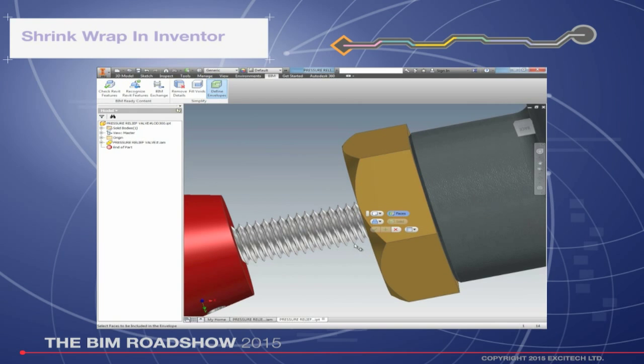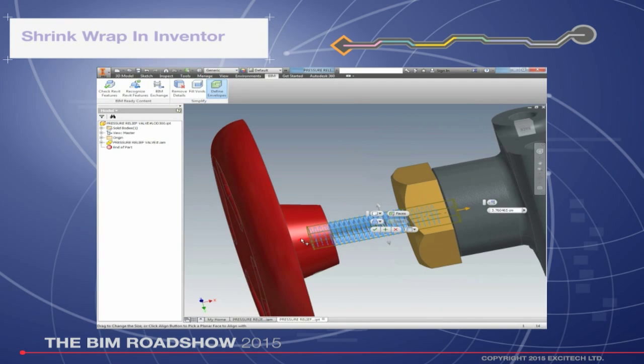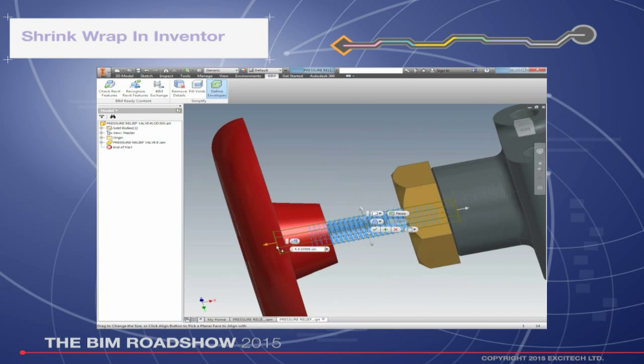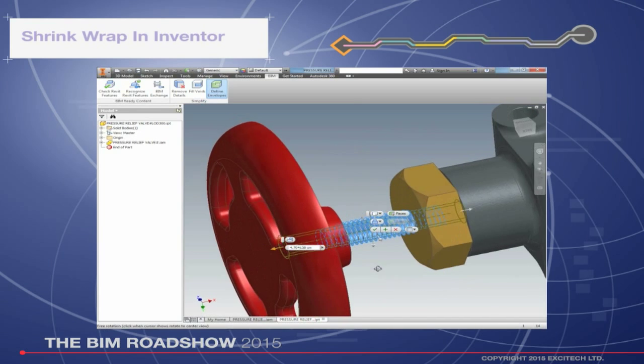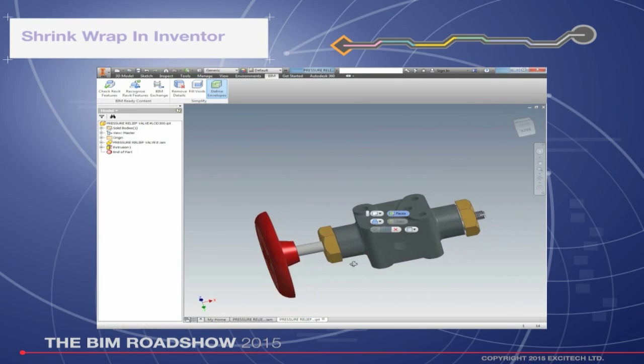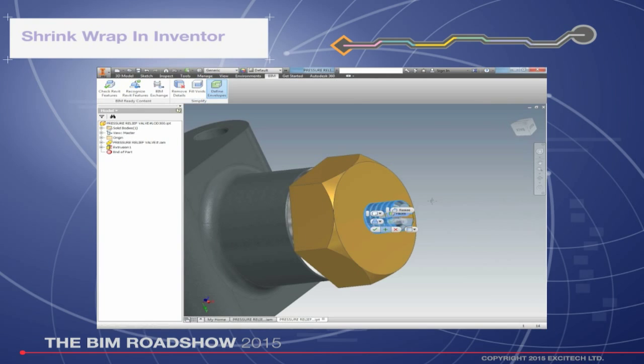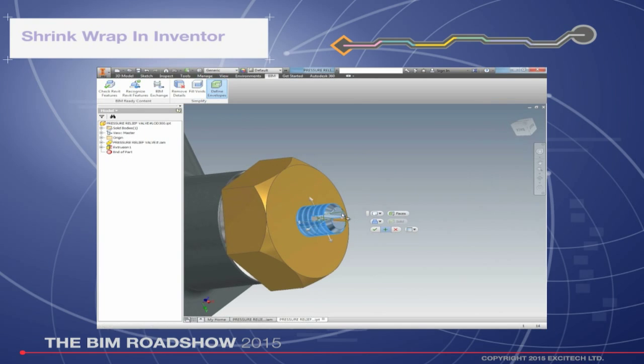And by using things like this, you can see this screw thread. I don't want 300 of them screw threads in my model, I just want a little cylinder. So it's actually replacing all the pictures of the screw thread with just one surface, so it'll have 3 faces then, just as a cylinder. And you'll see we'll tick there, and it will actually change it from a screw thread to a cylinder. That's simplifying that model. And we can take out the internals, so people can't manufacture this again.